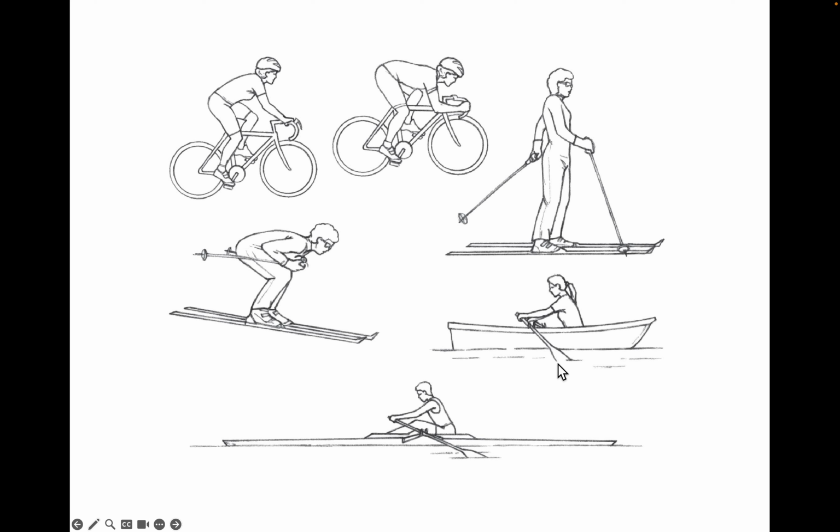And let's take a look at these two boats. This boat down here has a more gradual change in its shape versus this boat right here, which is more rigid and not as gradual of a change. Not only that, this boat here has a larger form drag because the boat is a lot higher out of the water versus this one's very close to the water. So this boat down here will have less form drag compared to this boat up top.